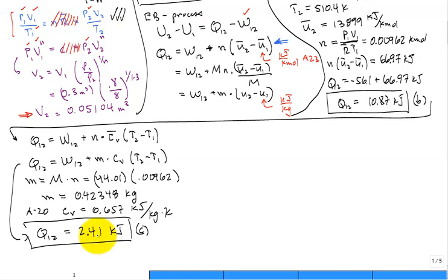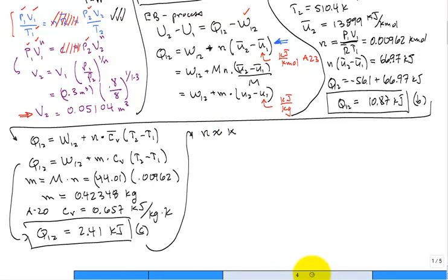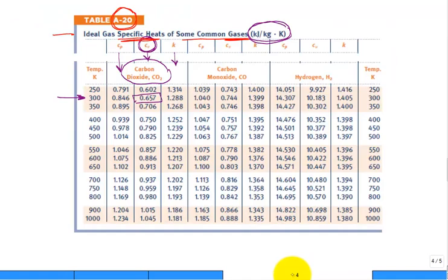One of the reasons is that when you have a polytropic process and N is getting close to the K value. So let me jump back over here. I hate to do that. You get sick and tired of jumping around. And this K value is in the low 1.2s, maybe 1.25, somewhere in that range.